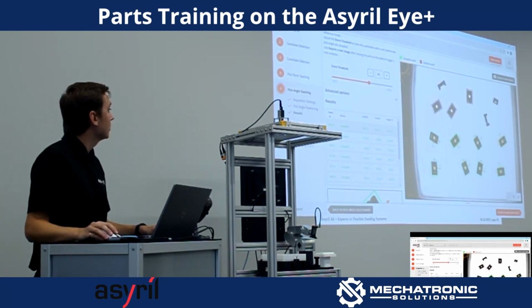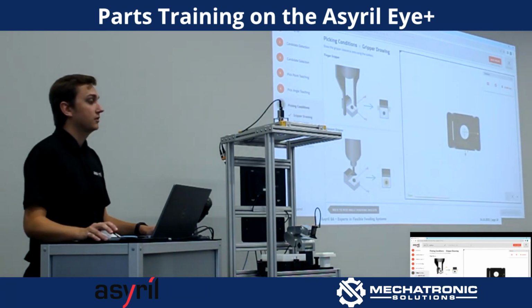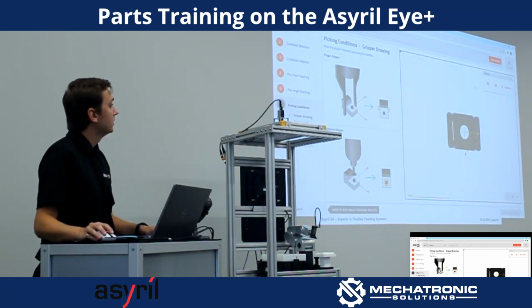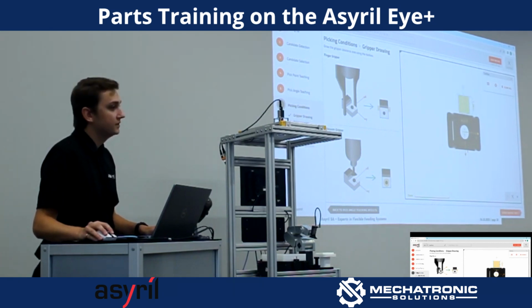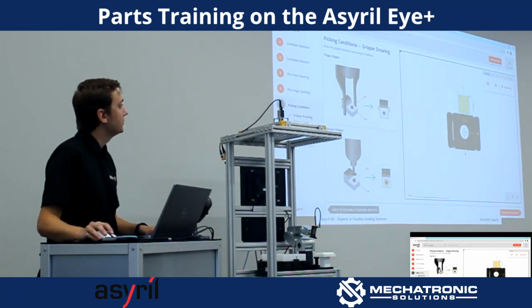So the step worked. The final vision step is setting your gripper drawings. And essentially what this is doing is creating an exclusion zone. So we've got circles for vacuum grippers and boxes for finger grippers. This one will use a finger gripper. You can adjust size, and it'll give you size in millimeters after you complete a vision calibration. So you can accurately size up your gripper however you want.